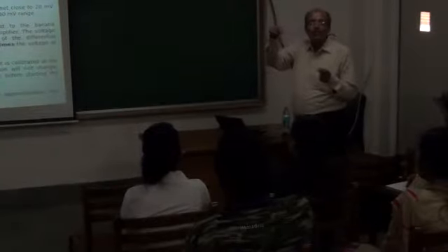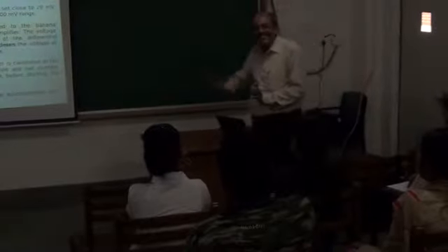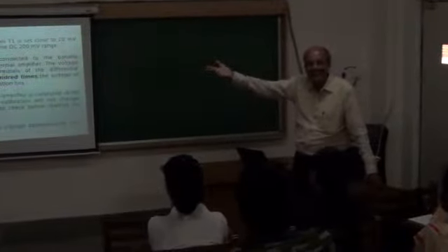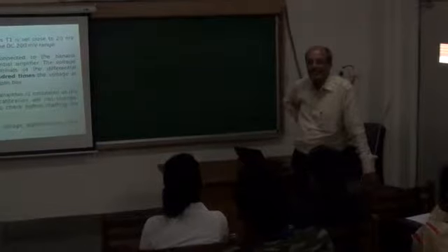So we are not talking about the resistances and other things. I simply wrote a formula that V output is equal to (V2 minus V1) into R3 over R1. I am sorry to tell you that I can't derive that formula. I simply copied it because from there I can explain that by changing R3 over R1, we can change the gain to 1, 10 and 100. 1 is not required because 1 means no amplification. So just 10 and 100, so we can change the amplification.